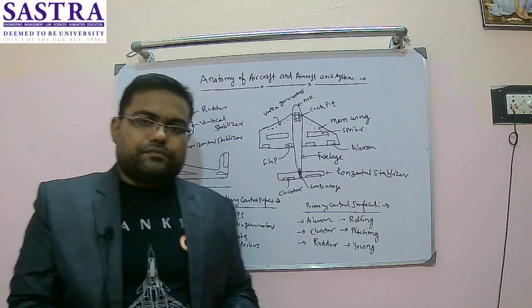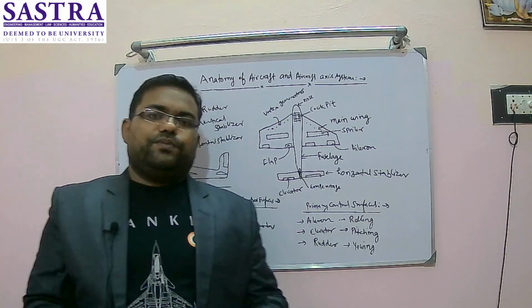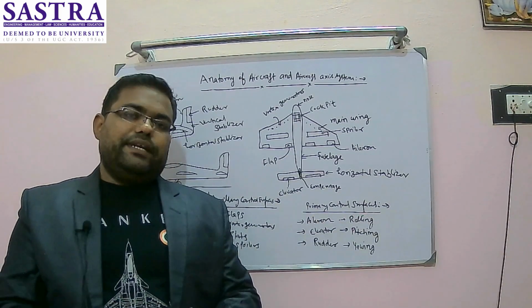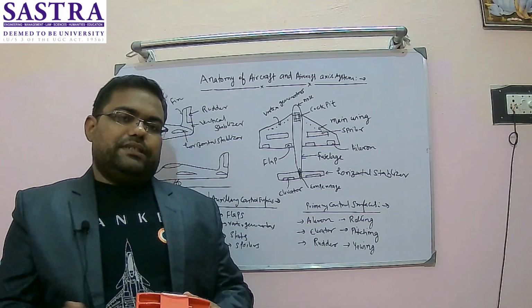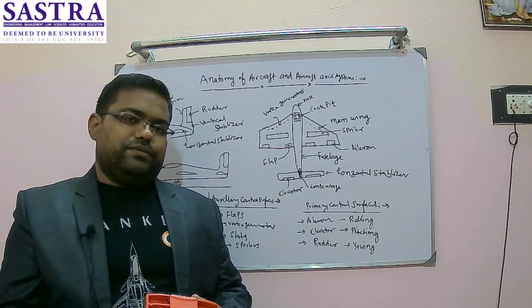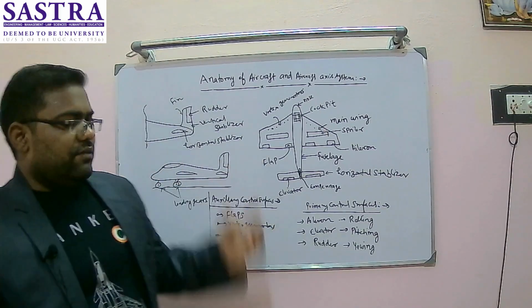How do they work? So this is the thing. I said the wing is responsible for creating lift. How is it actually creating the lift? If there is attached flow over the entire surface of the wing, then more negative pressure is generated on the top surface and positive pressure on the bottom surface, and I will get the lift. Right. That will happen only when my aircraft is cruising.